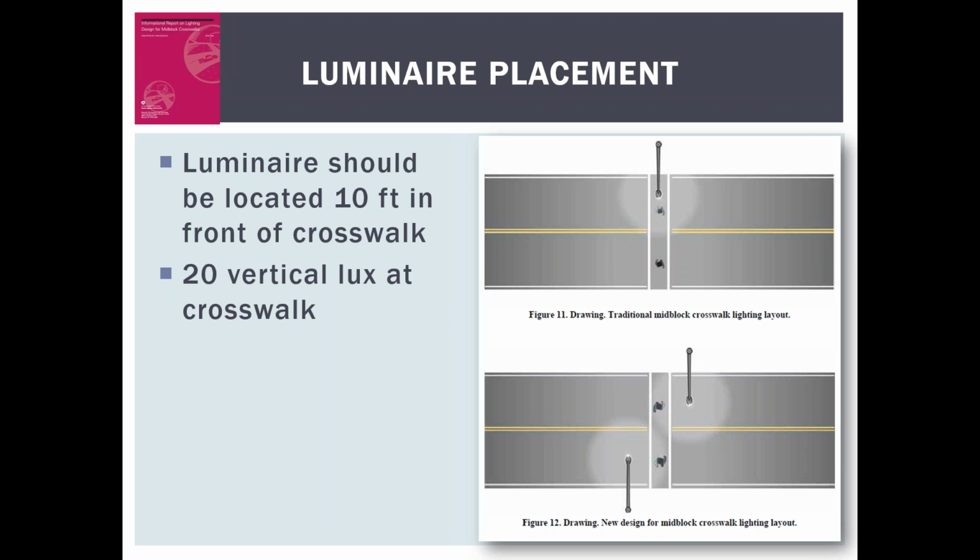If there's less people to maintain things, then they have to look at devices that last a longer period of time. But that is a big concern. Pedestrians are going to be at interchanges because that's the only place they can cross. So they should be expected. And just because they aren't there now, when you build an interchange or upgrade an interchange, somebody may come there in the near future, so that they should be designed to accommodate pedestrian crossings.